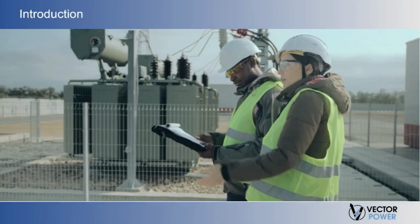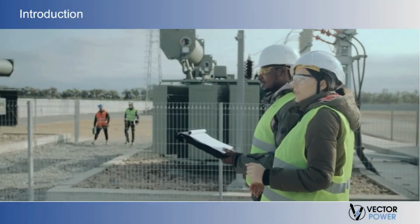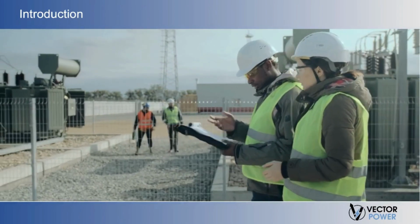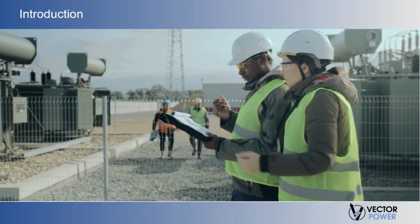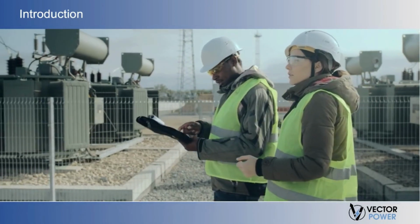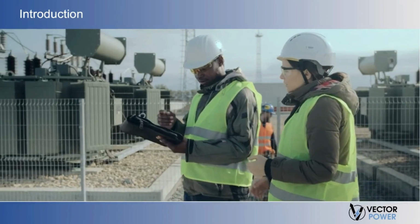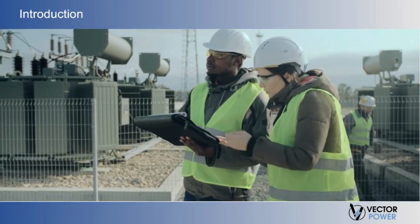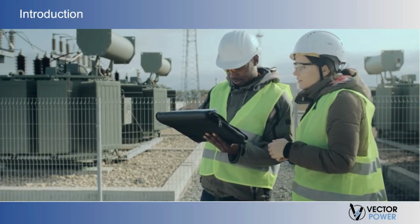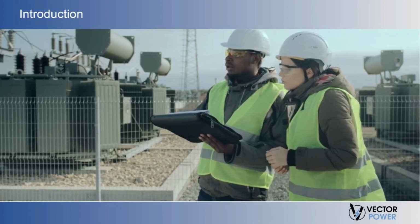Most electrical equipment failures are the result of insulation deterioration. Dissipation factor or power factor testing is one of the most effective and common ways to detect insufficient electrical equipment insulation. The test enables technicians to detect equipment insulation problems without making an internal visual inspection.